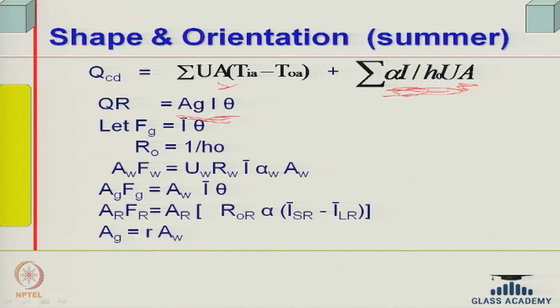bring in more heat. Now, I must introduce this terminology called solar gain factor. The solar gain factor is the ratio of the amount of solar radiation that comes in through the glass or transparent surfaces divided by what is incident upon it, right. Obviously, the area is there, so the area of the glass also comes into the picture. The intensity of radiation is in watt per meter square, and this is a fraction. So, this gives you the amount of radiation that will come in, the heat gain that would occur. So, we would like to minimize this as well.